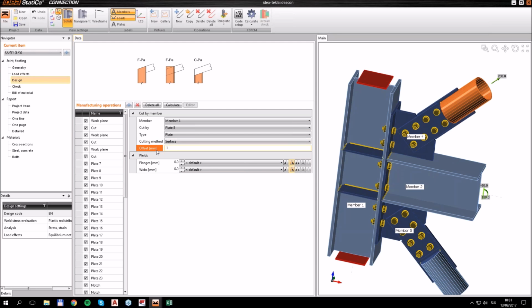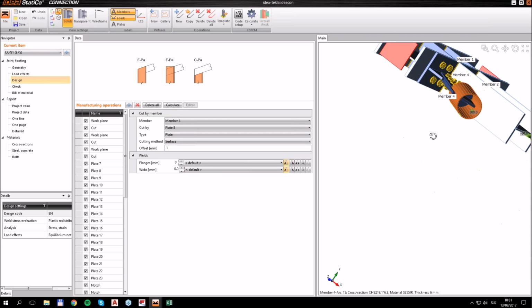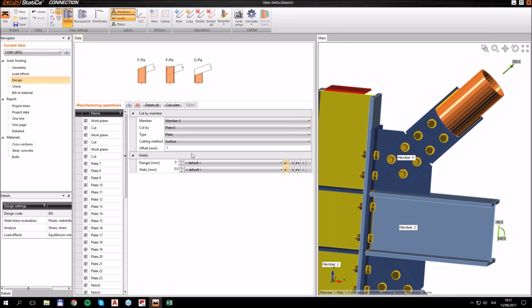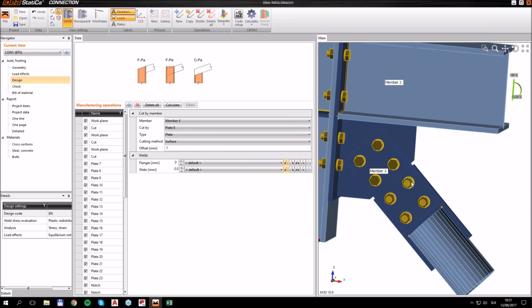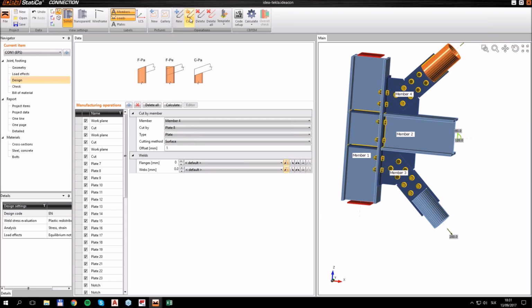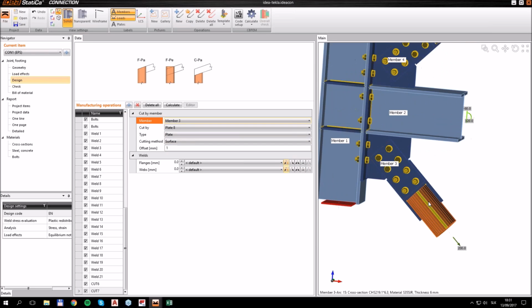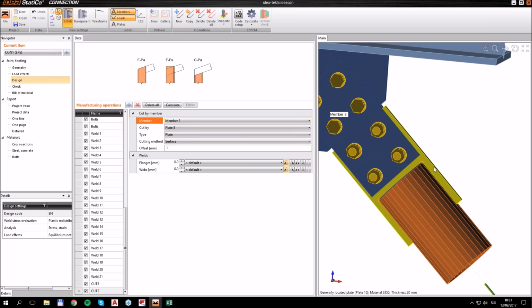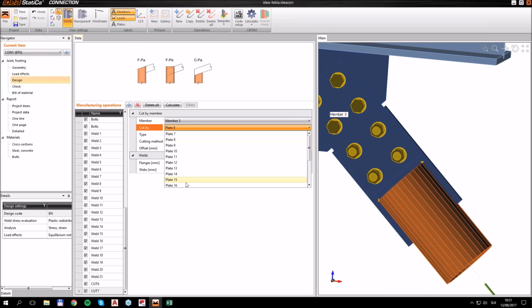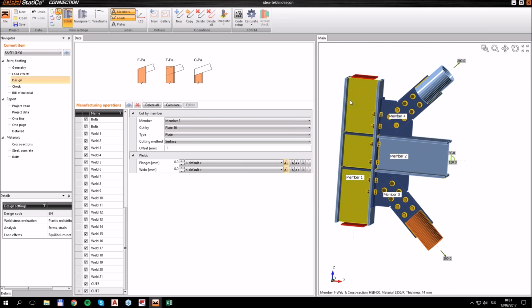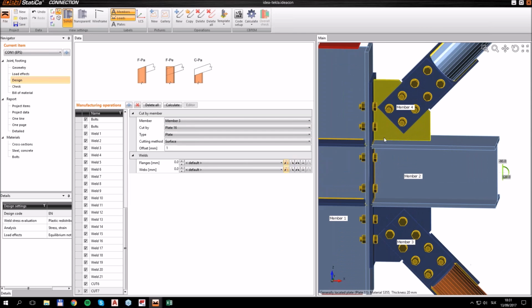And this happens sometimes. Yeah, and you see the welds are there. I won't bother with the size, and I will just copy this operation by the copy button and place it on the member 3, which will be cut by the plate 16, easily like this.